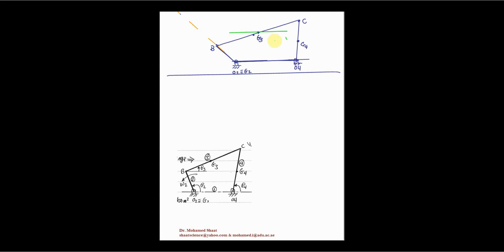You're gonna use the protractor, measure the angle, then mark a point. This is gonna give us a point here. Then connect this point to point G3 to end up with the direction of the acceleration AG3. Then over this line, you're gonna draw the acceleration vector. AG3 is gonna be this one. This is AG3. Make sense?